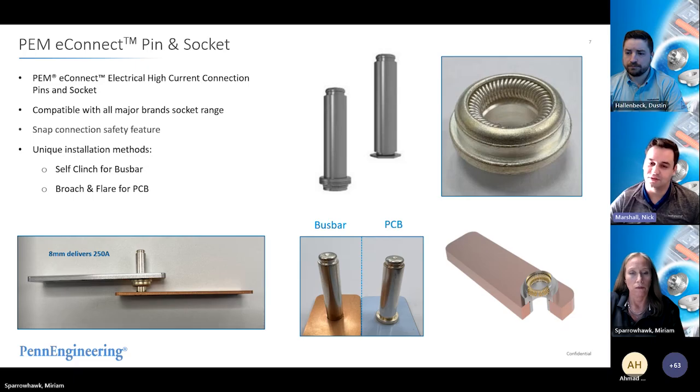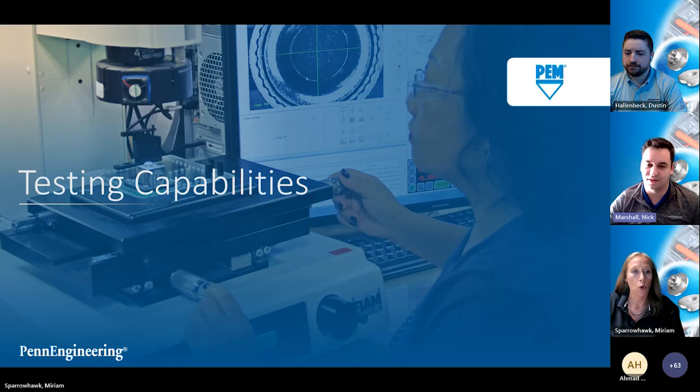Because that's coiled and those coils are laid over top of each other, they interference fit with the outside of that pin on multiple different points, giving you a large contact area in combination and making it flexible to be slipped over the pin without any extra